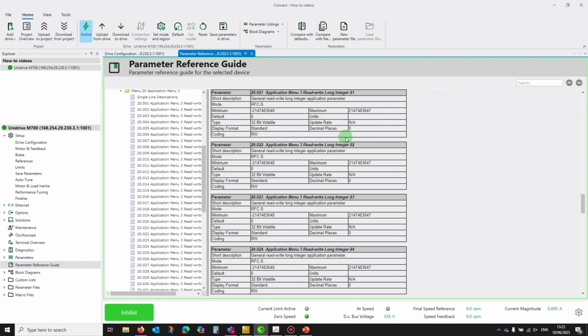It's put that to the top of the page, and you can see that it's a 32-bit type. That means it's either udint or dint. Now we can narrow it down. We can see that it has a negative minimum number. As soon as you see a negative minimum number, in this case very obvious because it's the full signed range, minus 2.147 billion to 2.147 billion, the full 32-bit signed range, you know that this is going to be a dint.